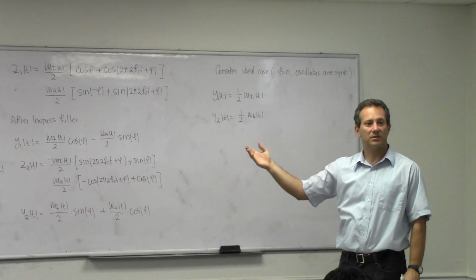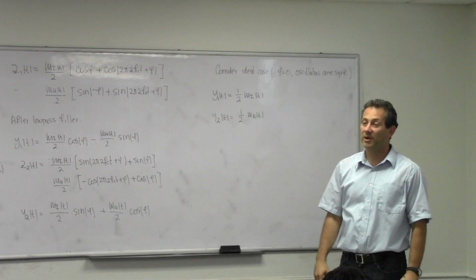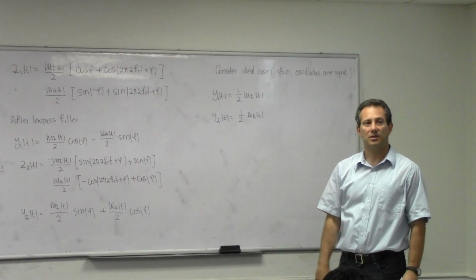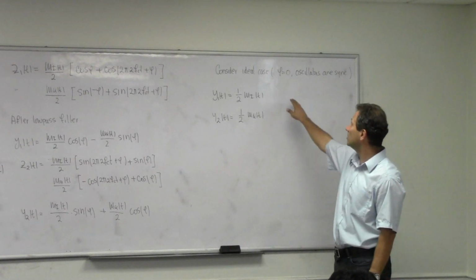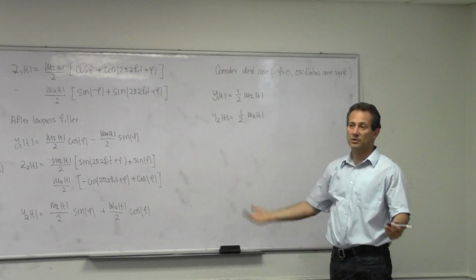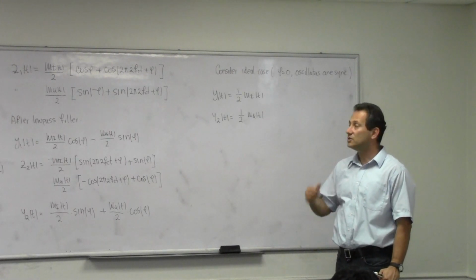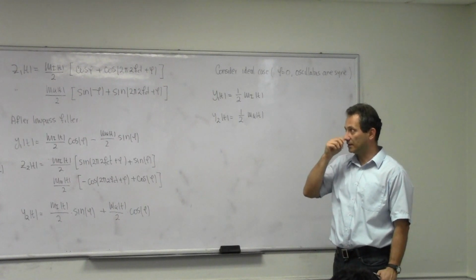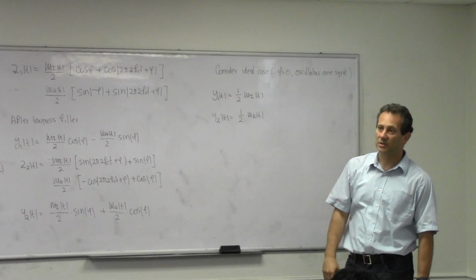So if I manage to synchronize these two, guess what? I'm doubling the capacity of my channel. I'm using exactly the same spectrum to send two signals in power, right? And if I manage to synchronize the oscillators, they're not interfering with each other, right? And this is used quite a bit, especially in pretty much all digital modulation schemes.